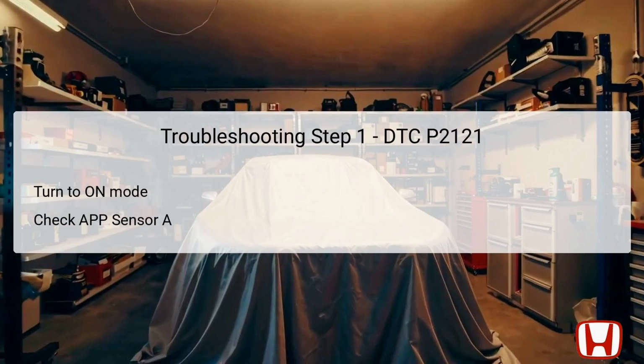The first step in troubleshooting DTC P2121 involves verification of the problem. Start by turning the ignition to the on mode without starting the engine. Next, use the Honda Diagnostic System, HDS, to monitor the parameters of the APP Sensor A. Check the recorded voltage from the sensor.